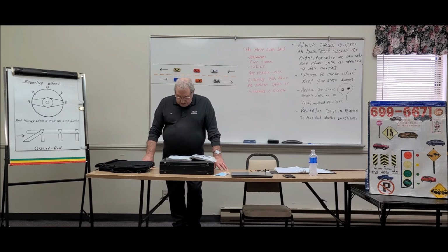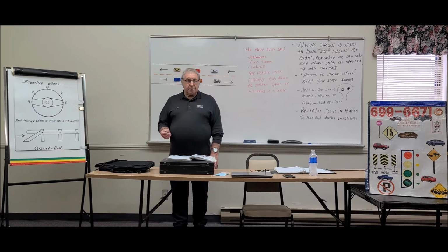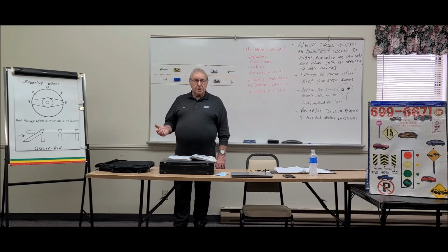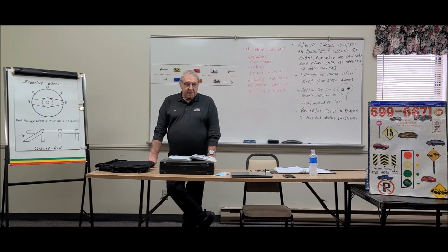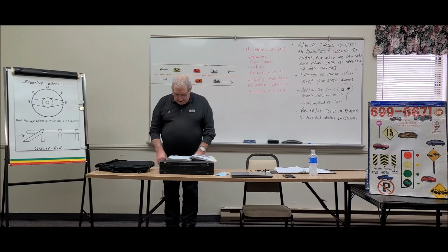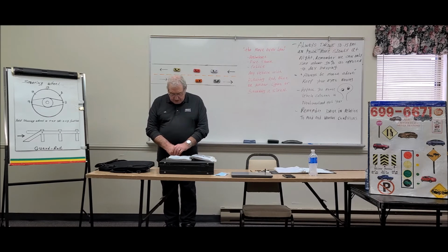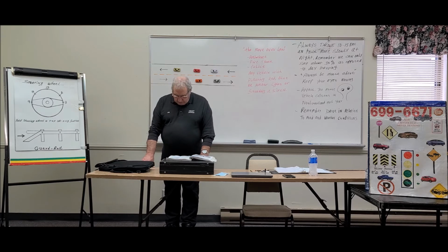The start position, of course, is spring-loaded. Exert an extra pressure to turn the key to this position, and once the engine starts, after a couple of seconds or so, you just let go of the key and it flies back to the on position. It's spring-loaded there, and you don't have to worry about the key coming back to the on position. It'll do so itself. If the engine is not operating, wait several seconds before restarting. Some vehicles require returning to the off position before restarting.